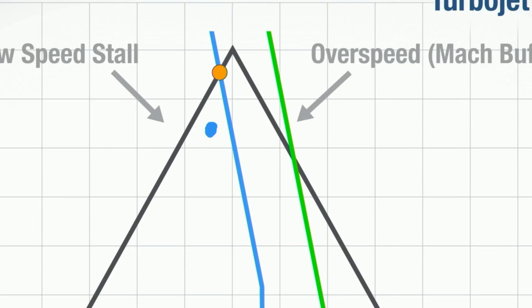And one of the things to think about is the jet engine's power output depends on a lot of factors, temperature, density of the air. But one easy thing that you can take a look at is the air becomes less dense. The jet engine either needs to spin it faster, essentially, to try to get the same amount of compression, and eventually you run out of the ability to do that. So as you get to some point, as the air becomes less and less dense, the jet engine starts to lose power. Well, as the air becomes warmer, it gets less dense.